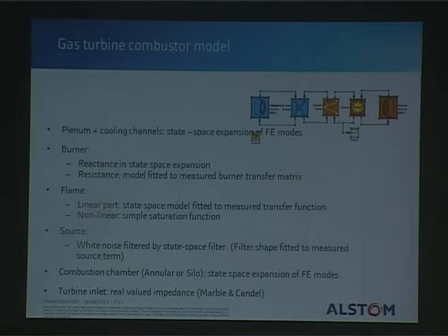The linear part we get from state space equations fitted to the measured flame transfer function. However, for the nonlinear part, we put in a simple saturation function. Physically, this is not really correct, but we don't have the means to do that more correctly. I will come to that point later.